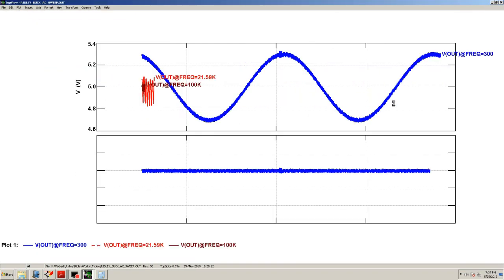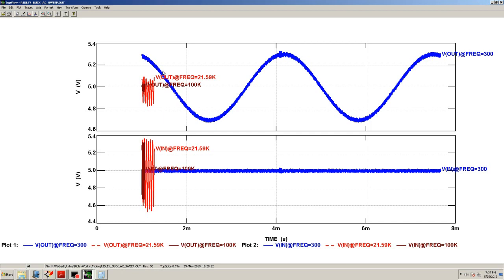Okay, so this is the lowest. First of all, this is telling me that I have a good signal, and I believe the peak to peak is going to be 600 millivolts. But there's supposed to be a wiggle here, and you hardly see any wiggle here. So you would have to expand this to see an AC.